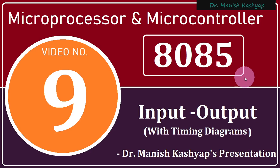We have seen that timing diagrams are important and they give us an idea of how things are happening inside the microprocessor. They have a mix of both kinds of information: software as well as hardware. From the software perspective, we know which signal will be on or off under what circumstances. From the hardware perspective, we came to know which signal was triggered under what circumstances, in which particular T state it was triggered, whether on a rising edge or a falling edge, or maybe on a lower or higher level of voltage. So we saw that information there, and